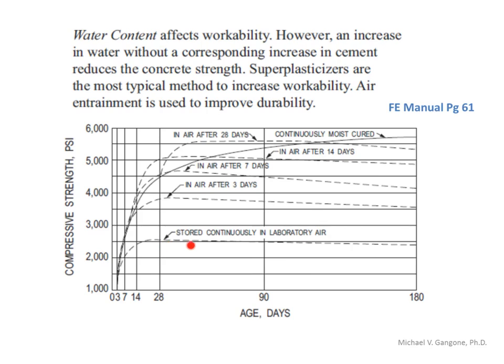So the concrete's not going to hydrate appropriately to gain the appropriate amount of strength. All right, so it's very important that we have proper methods of curing. And again, moist curing is the best form to do, making sure moisture stays in. And you can see that's this curve here, and that's where we're really gaining the most amount of strength using this particular curing method. Okay, so curing method has a huge effect on the overall final strength and final product, so to say, that we get in the concrete.